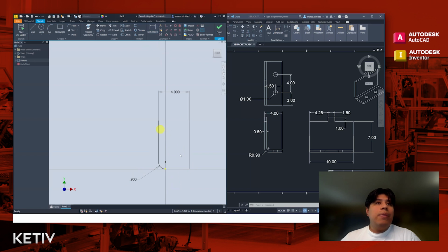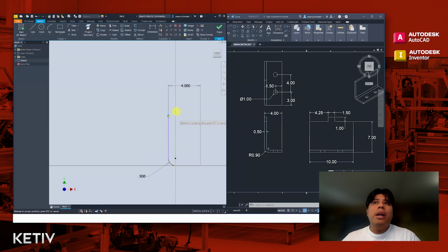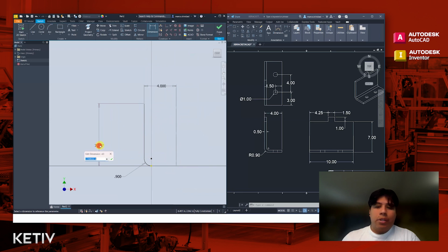And then it does look fully dimensioned. As you can see, the line went from purple to black. That's indicating that these are fully constrained. Although you can see I'm still missing 1 dimension from looking at the bottom right. And that, I believe, is going to be this vertical. So you can see that this line can still move up and down. So I do still need to add in a vertical dimension or a constraint to finish up this line. So I'm going to add in this last one, which I believe is 8 inches.